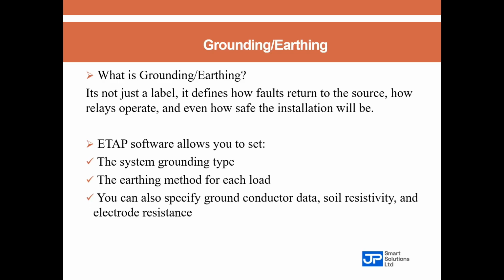You can also specify ground conductor data, soil resistivity, and electrode resistance. All of these determine the reference point of your network. Unfortunately, most engineers skip this step.